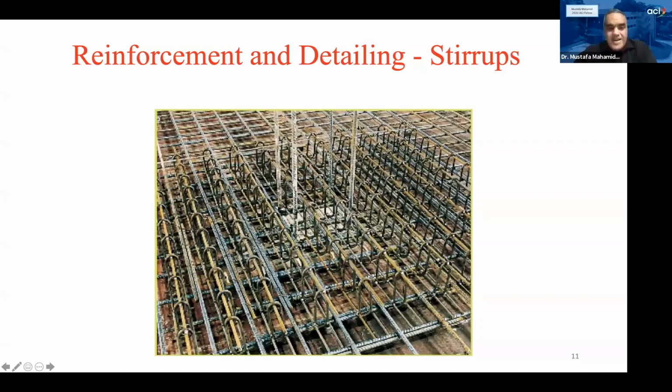My apologies again. They go around the longitudinal bars, or actually the longitudinal bars will keep them together, and we have to maintain the contact between the stirrups and the rebars. Okay, so if we look at that closely, that's what has been used before starting to use the studs. So we have a movement at the end of the bend. There will be some movement here at the end of the bend that's expected.